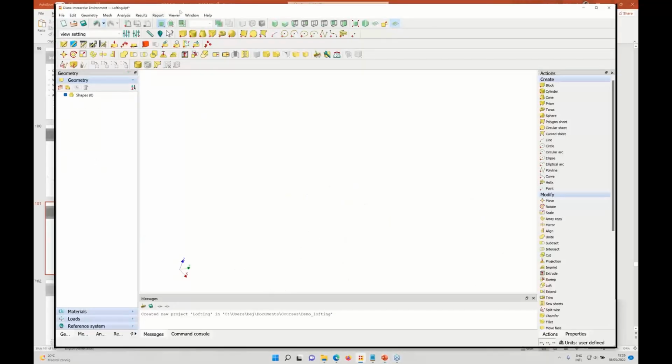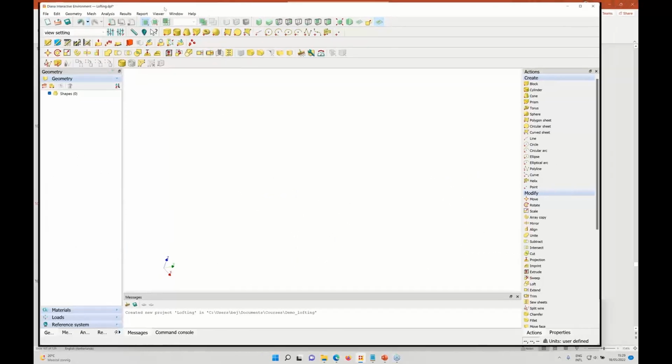I have already a session open. For this, I have already created a project. You are familiar with that now. You start a new project, you give it a name, you give a dimension. In my case, it's a 3D project. For the type of analysis, I put structural, but today I'm not going to perform any analysis. I will just show you how to generate geometry bodies using the lofting option. And so the analysis type is not that important. And we also set up our units. In these examples, we go for meter, kilogram, Newton, second, Kelvin, and degree.